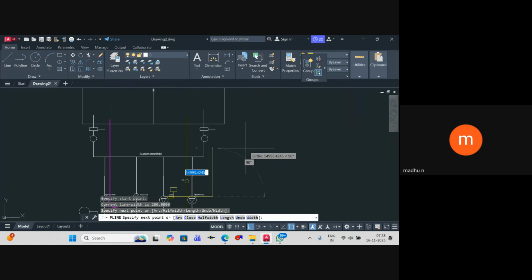Is there a limit on the number of bends for the exhaust, or do we have to restrict it? Try to avoid the maximum number, but as such around 4 or 5 we have given till now and we have never faced any problem. So it's better we speak to the OEM of the diesel engine. There's no such rule. It depends on the capacity and the brand as well. So we have to speak to the OEM, but generally 3. In my previous project also, once you raise it, anyway you have to take a bend right or left. One we have taken, second.